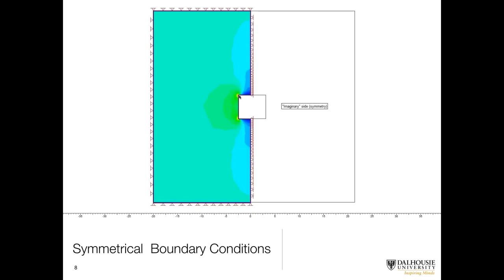So if the model geometry, in this case a square tunnel, and this would apply for a circular tunnel or rectangular tunnel or whatever, stope, anything like that, as long as conditions are the same on both sides of the problem, then you can simulate it with a plane of symmetry right through the middle. And these roller boundaries mean that this boundary cannot move in the x direction, fixed in x, but it's free to move in the y direction.